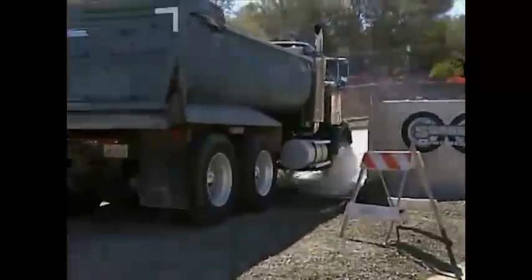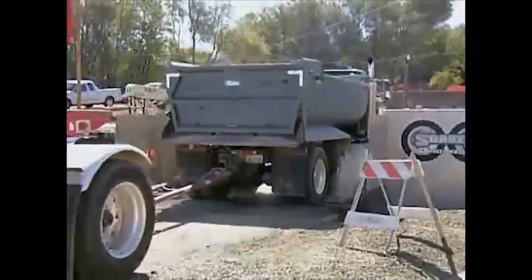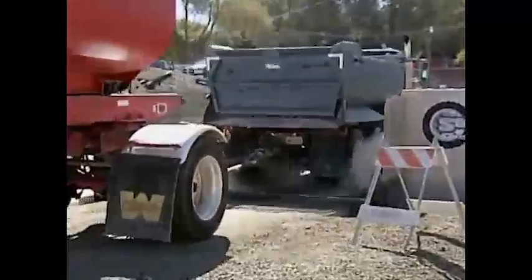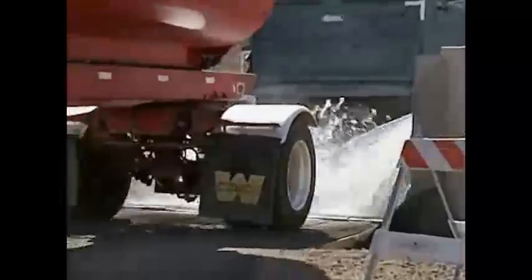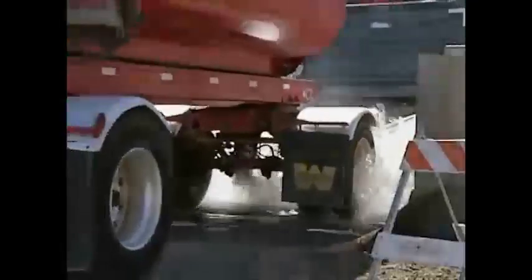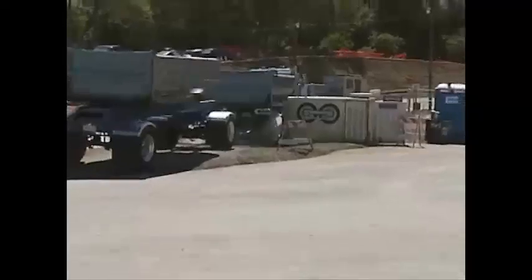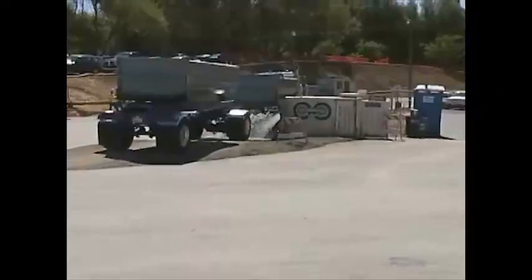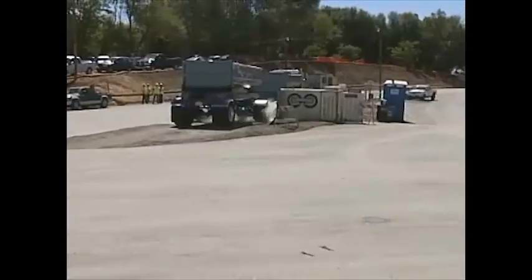A tire wash best management practice is usually located at a stabilized construction access point and is designed to remove sediment from tires and undercarriages and to prevent tracking of sediment onto the roadway. In order to prevent the release of pollutants from the tire wash, wash water is conveyed to a sediment trap or basin. A tire wash BMP is implemented on a project-by-project basis with other BMPs when determined necessary and feasible